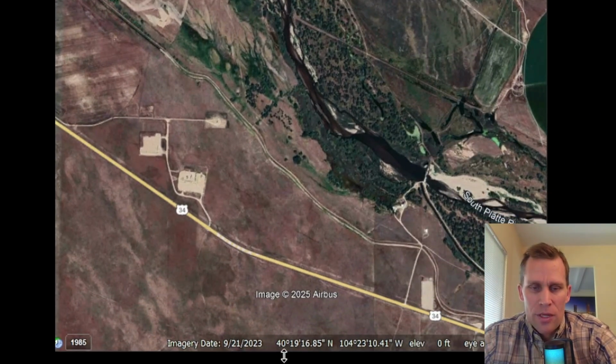On the bottom of the screen, you see a latitude north and then a longitude west. So that would be positive 40 degrees and so on, negative 104 and so on, because west is the negative longitude value. I'm going to go ahead and just put my cursor over the river and then take that single point as my top left corner and my bottom right corner. So it's really just a point that I'm going to be asking HEC-RAS Mapper to give me the USGS files for.